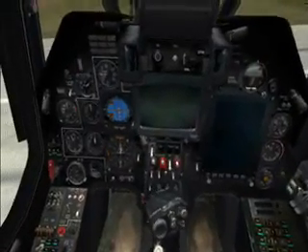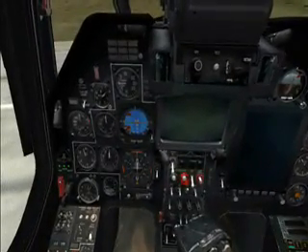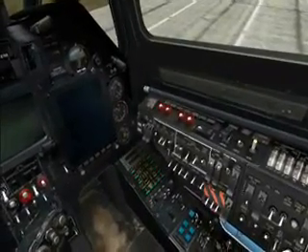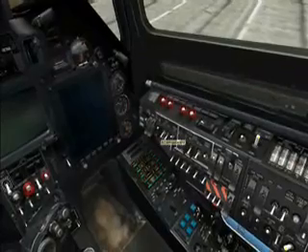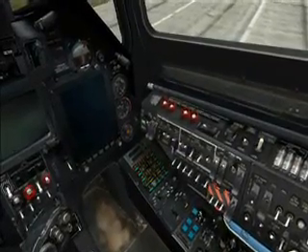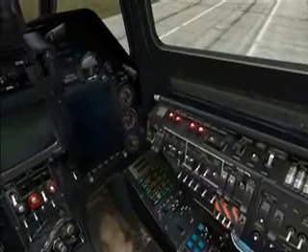And with both engines up and running fully now, the shaft is actually turning the generators, which is then supplying electrical power to the onboard batteries. So we can go ahead and enable the batteries, and with that we can disable external power, which we just did. So at this point now we're operating fully on internal electrical power.